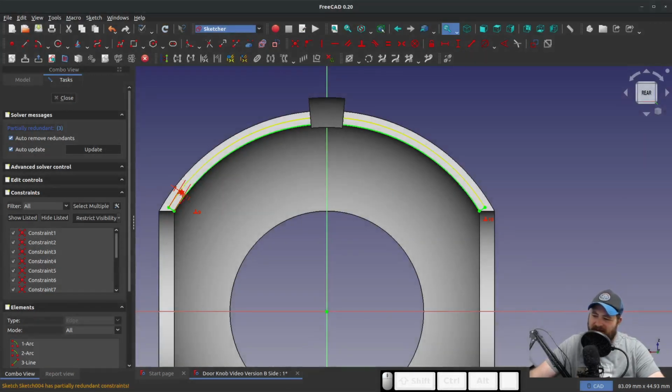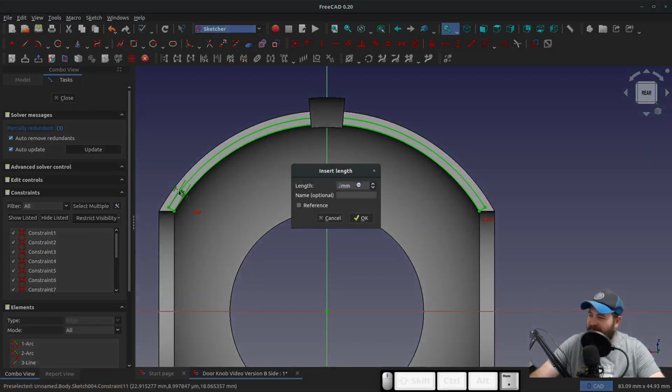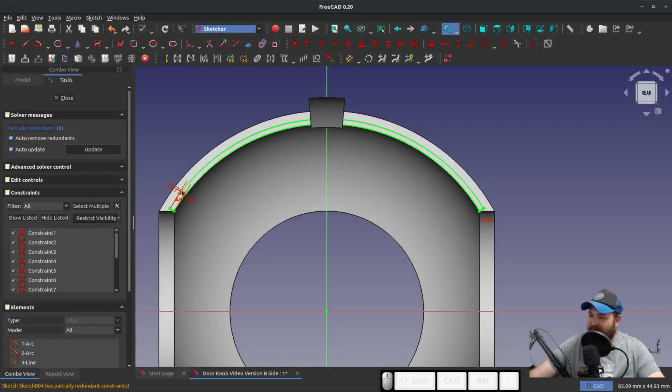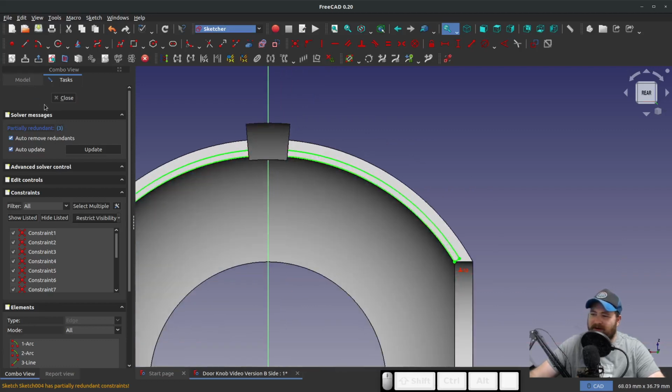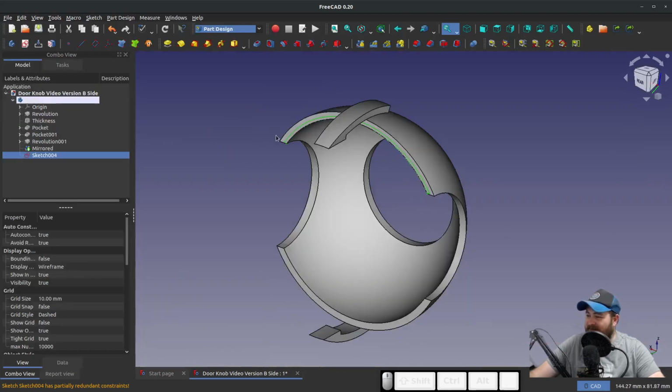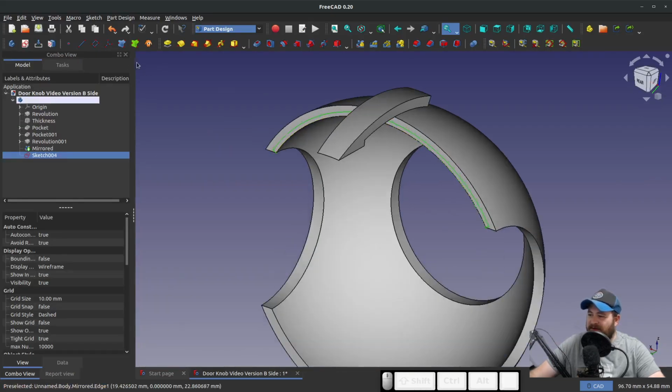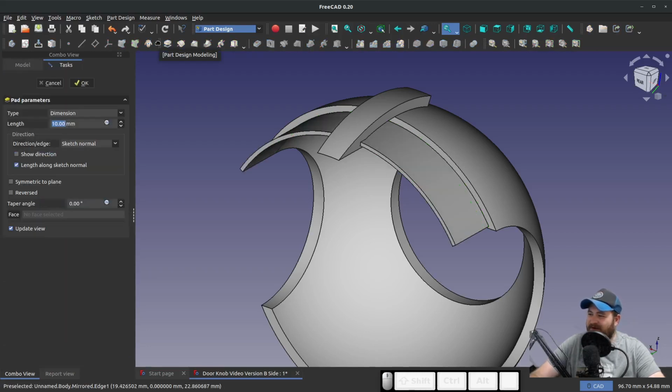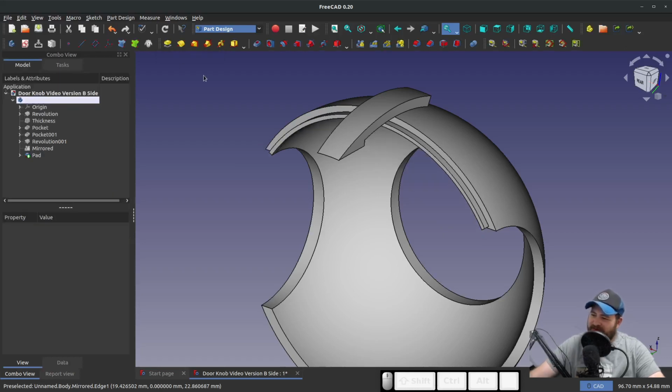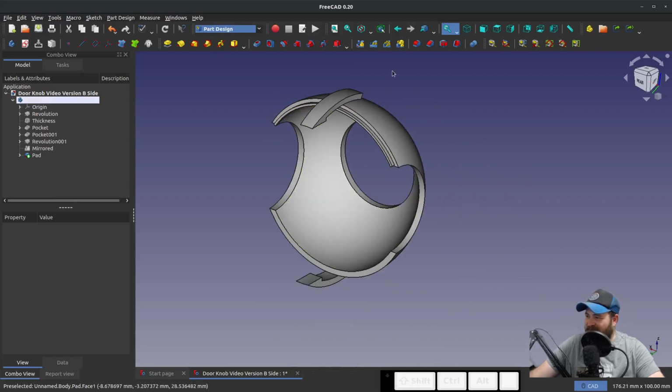In fact, we gave our groove a distance of 1, so to prevent a possible interference, I'll make this point 0.75 millimeters, or 3/4 of a millimeter. We'll close that. And let's go with a boss here of, let's see, we did 1.5 on one, so I'm going to say 1.25 on this one, just to make sure we don't start to interfere with that chamfer section.